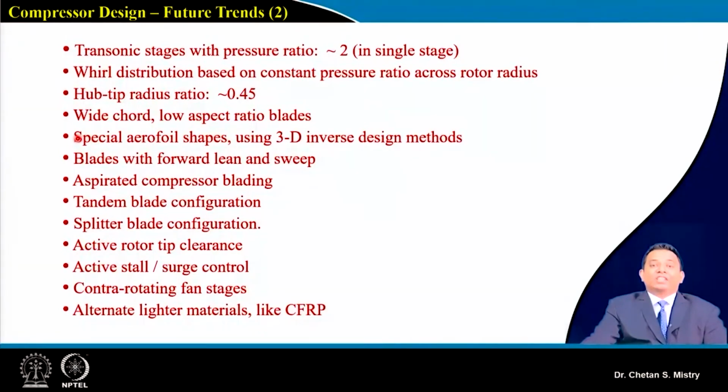In one of our lectures we discussed the inverse design method. That may be working fine when we are talking about design condition, but when it goes under off design condition, that means a change of speed or change of mass flow rate, then it may go very odd, not like your conventional compressor. And that's the reason why we need to look at all those aspects when we are doing our design for the blades.